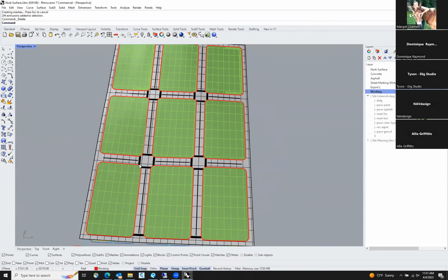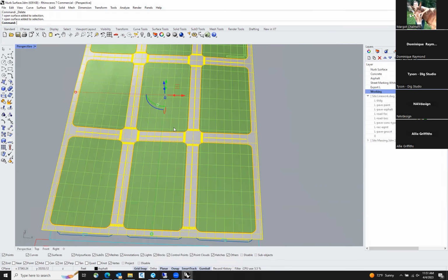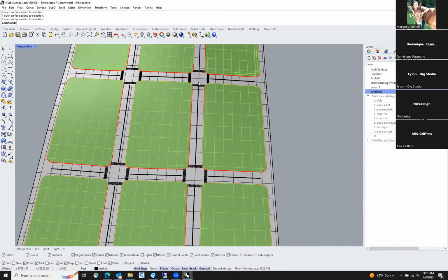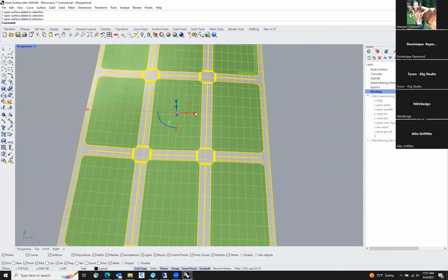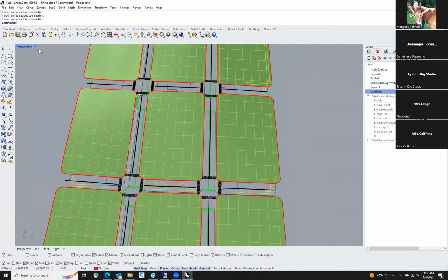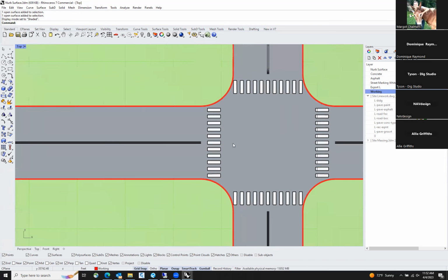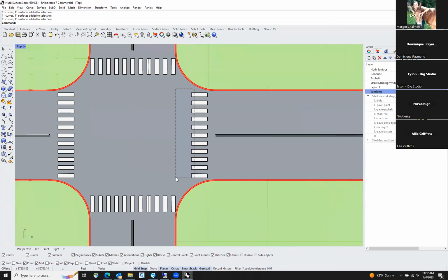So as you can see, it split that surface based on those extruded shapes. And I love gumball because it's really easy to move stuff. So instead of selecting each one of these individual squares, I'm gonna just pick this up and move it 2,000 feet in the X direction. And I'm gonna go to top view, turn into shaded. And as you can see, it becomes a lot easier to do these wholesale selections when you aren't battling another surface that you could potentially select.